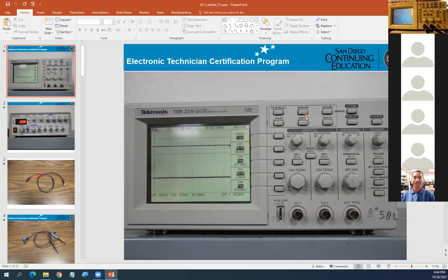You press that if the signal goes beyond the screen. Now, they cannot go beyond. When you press auto set measure, they are already adjusted. So you don't have to press auto set measure, right? They already display everything you want. Correct. So if nothing's displaying, press auto set measure, try to get it on the screen, and then adjust. The thing is, when you set auto set measure, the scope will adjust everything you can see.